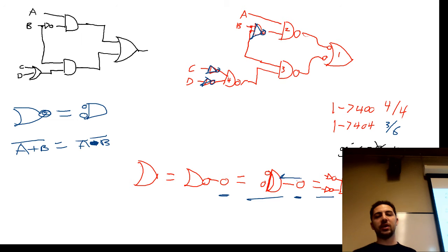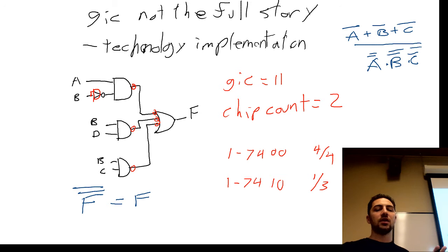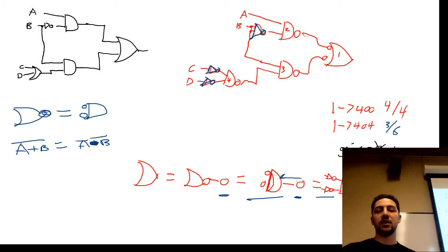The only criteria that we have not tested is the gate delay, the propagation delay. So this has a propagation delay worst path of 3. If you follow through the OR, through there, and then that inverter, that's 3 gates. This would have quite a bit longer, 1, 2, 3, 4. Well, longer. It would be a longer propagation delay time. But that was not the criteria we were given. Propagation delay was not even a consideration. So, yeah, technically one of them is better in propagation delay.